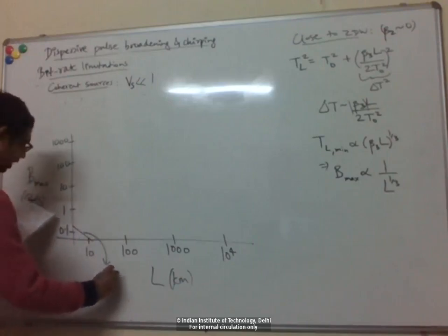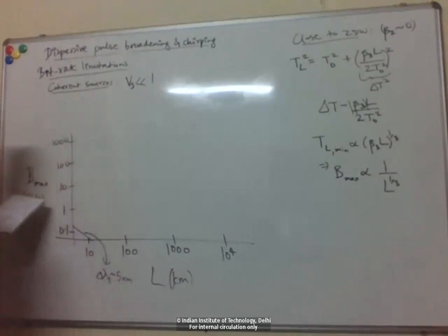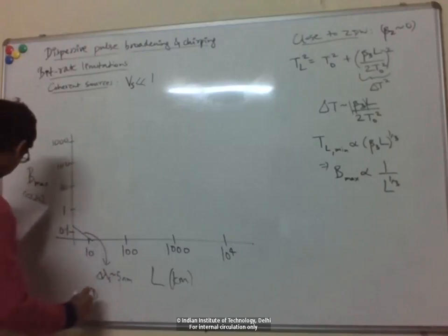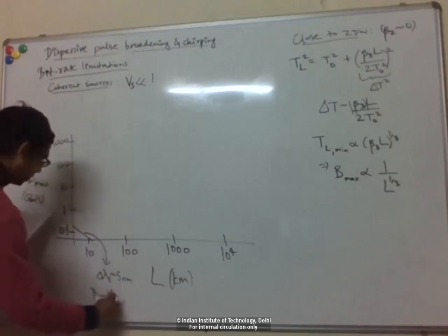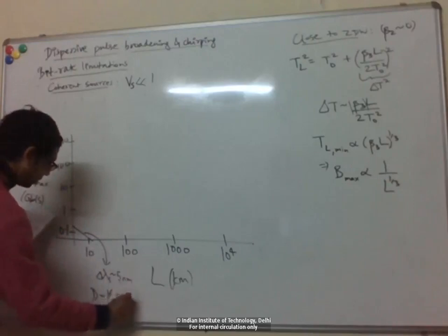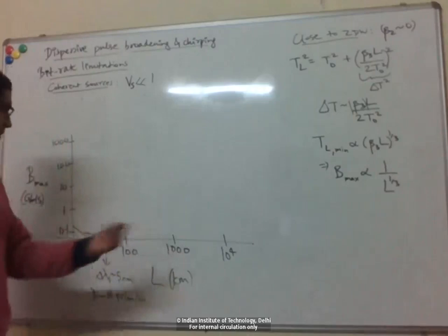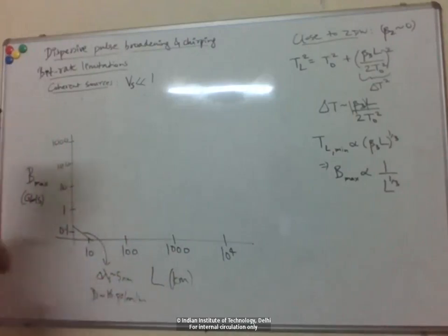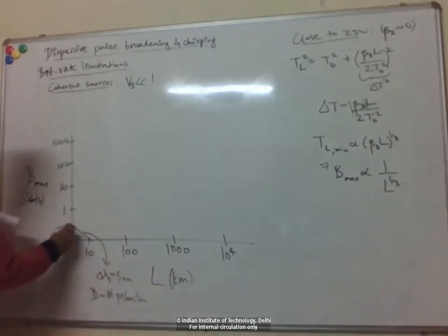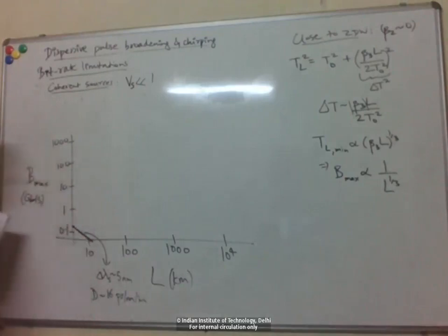Okay, so this is for let's say a laser diode with 5 nanometer bandwidth, and the dispersion coefficient is about 16 picosecond per nanometer per kilometer. Basically, if you take 1550 nanometer wavelength for a conventional single mode fiber, this is the dispersion value, right? So you can see that this is very bad. I can go for maybe 10 kilometers at less than a gigabit per second.